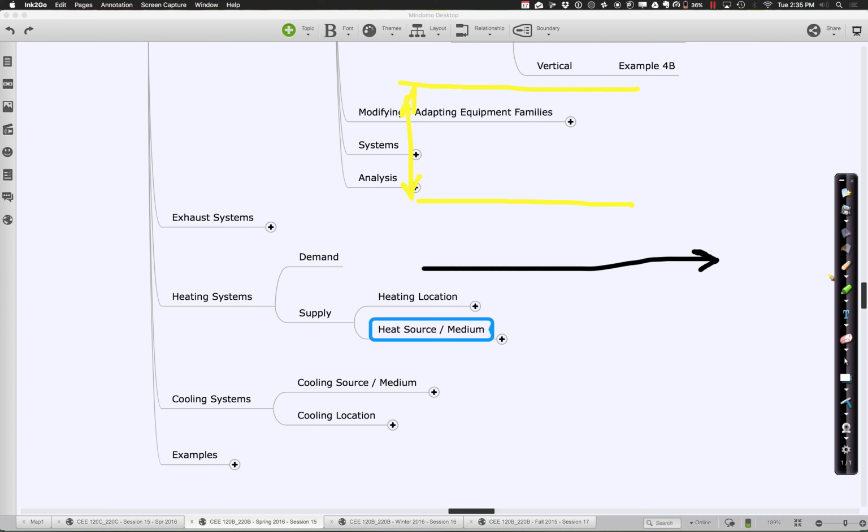Okay? So there's this upper limit. I'm going to say that is my cooling set point. If the temperature ever gets higher than that, I'm going to turn on the cooling. On the other side, I have the heating set point. So if it gets colder than 68 or 66 or something like that, on the other side over here, you're probably going to want me to turn on the heat, because you want to stay within that comfort range.